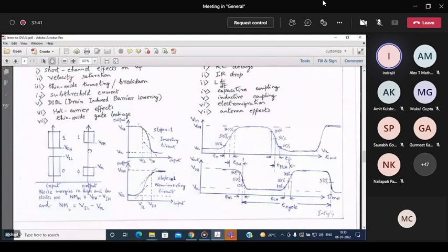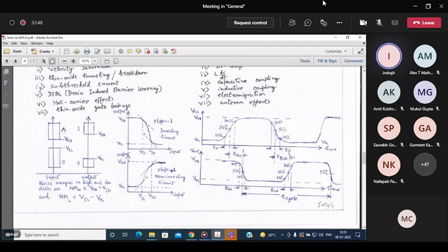Again, by way of some recapitulation, here we bring different salient voltages to your attention. You know all about that, I'm sure, but just to touch upon the basics. So this is, let us say, the logic 1 domain. This is the logic 0 domain. We just show by two rectangles. That means there is a range of voltages. When you say logic 1 voltage, a particular component at the output, we are seeing logic 1 and logic 0. It does not mean that always we shall have a perfect 5 volt or perfect 0 volt.